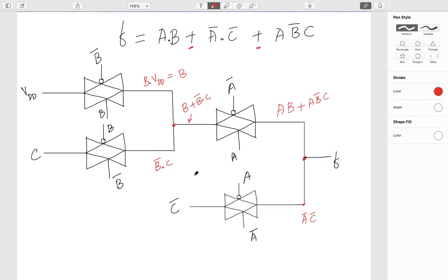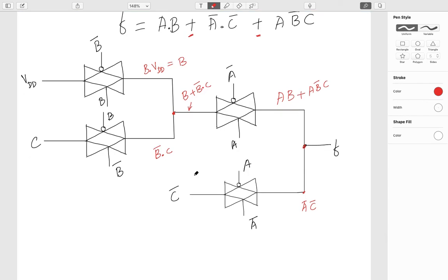Otherwise, if we are doing a simple convolution, we should know what the past values are. So the pass transistor happens to be very useful for designing sequential logics. I will show how to implement the D flip-flop and D latch using the pass transistor.